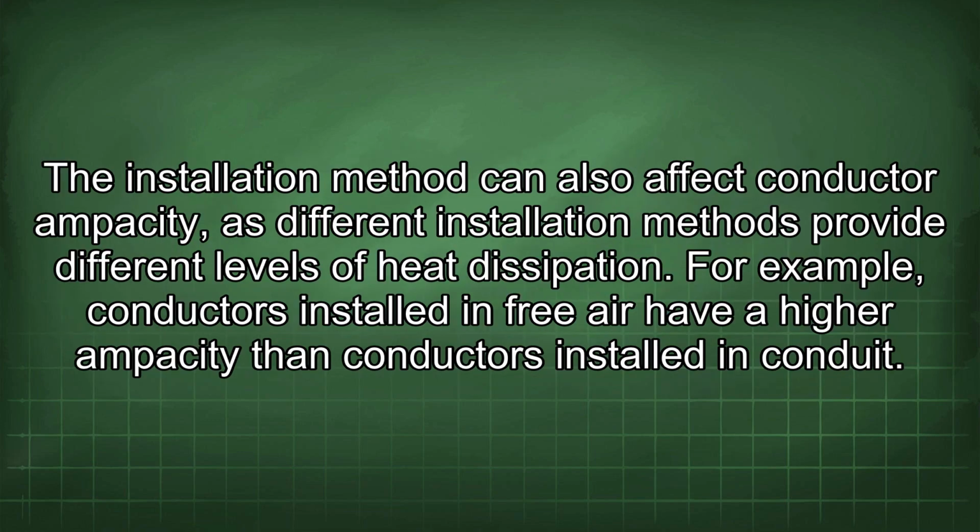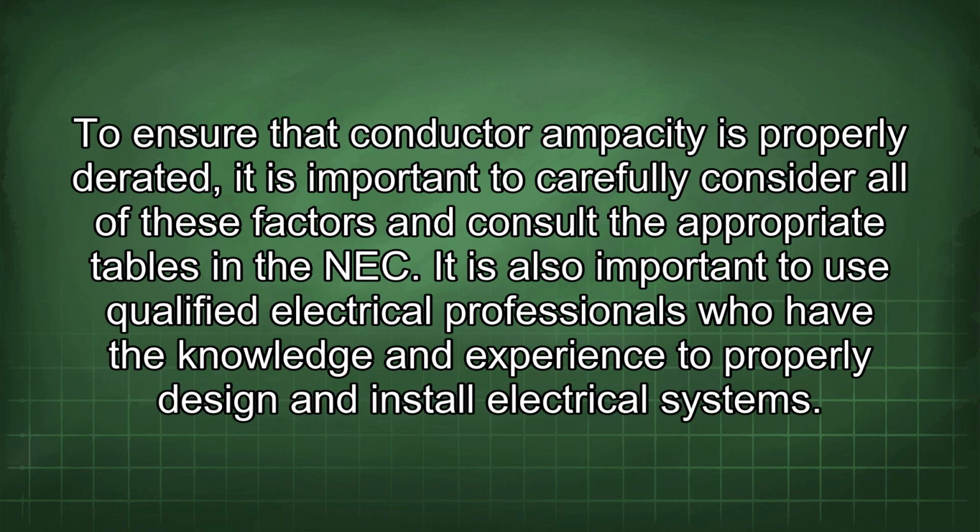The installation method can also affect conductor ampacity, as different installation methods provide different levels of heat dissipation. For example, conductors installed in free air have a higher ampacity than conductors installed in conduit. To ensure that conductor ampacity is properly derated, it is important to carefully consider all of these factors and consult the appropriate tables in the NEC.